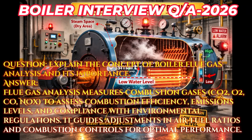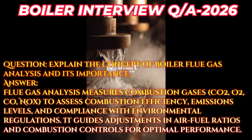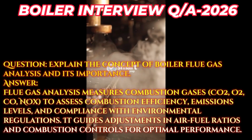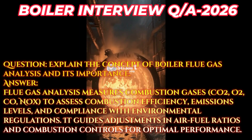Question: explain the concept of boiler flue gas analysis and its importance. Answer: flue gas analysis measures combustion gases, CO2, O2, CO, NOx, to assess combustion efficiency, emissions levels, and compliance with environmental regulations. It guides adjustments in air-fuel ratios and combustion controls for optimal performance.